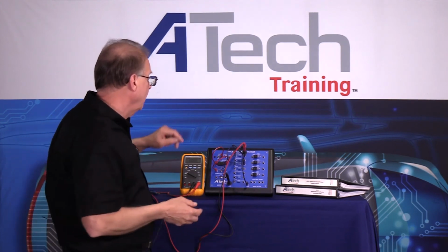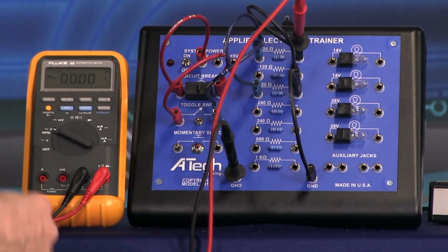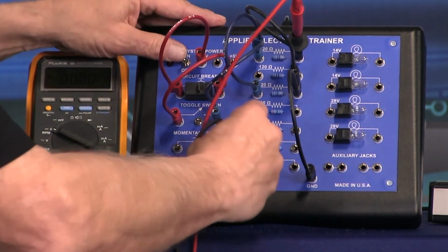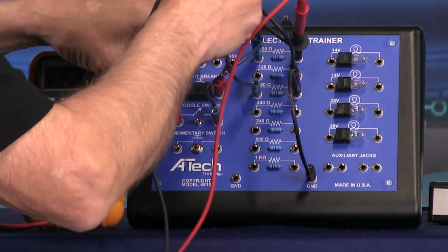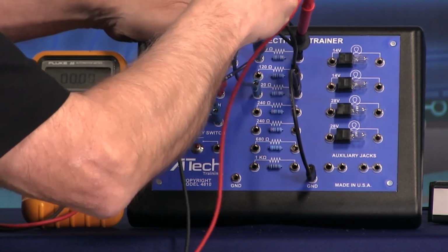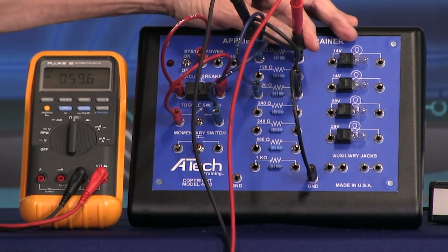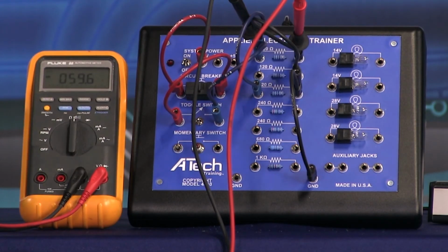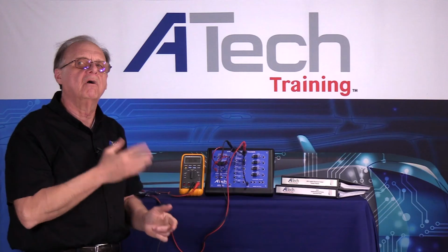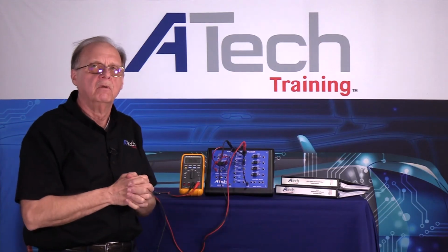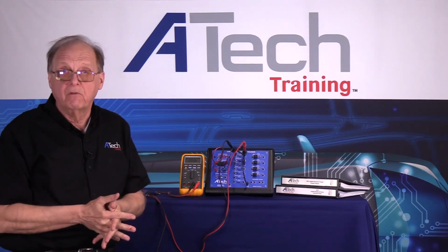So if I'm looking at this, I want to see the ohms across here. What I'm going to do is just do my old nice little thing up here. I'm going to go across. All right, so I've got 59.6. How can I have 59.6 on a 120 ohm resistor? That's because the circuit's in parallel.